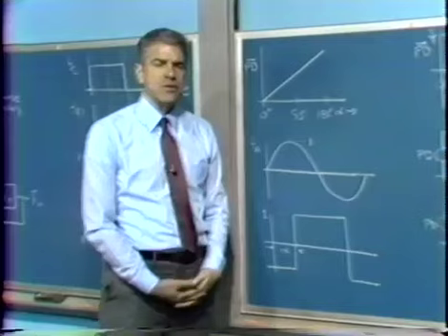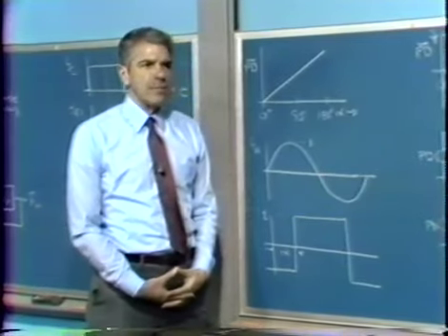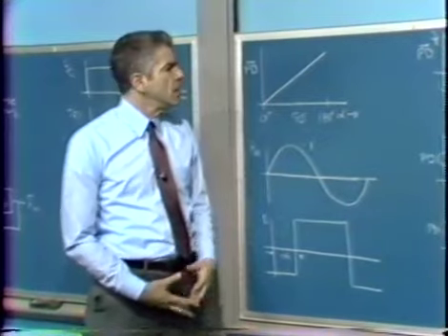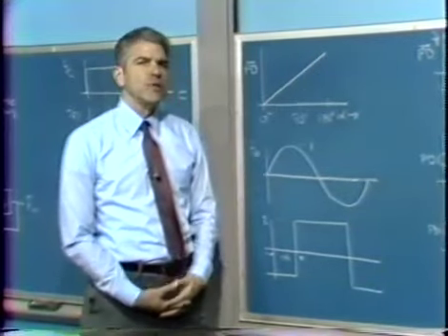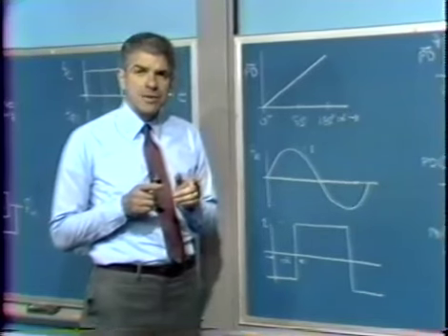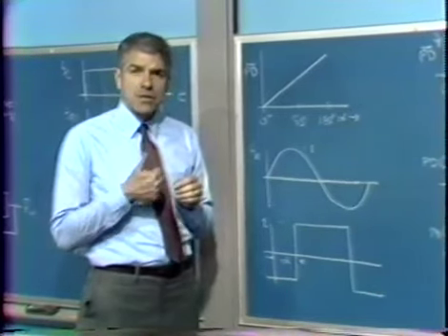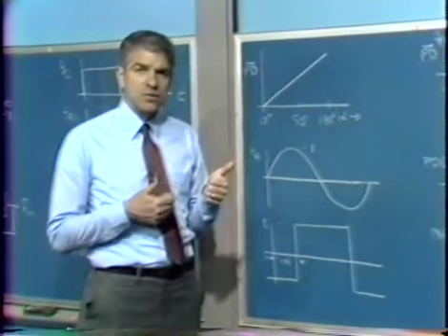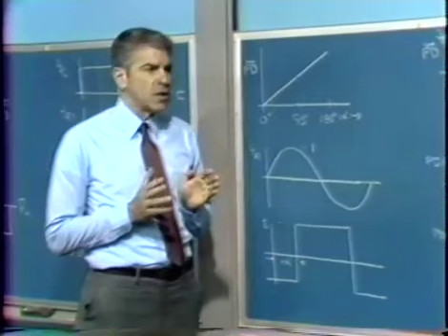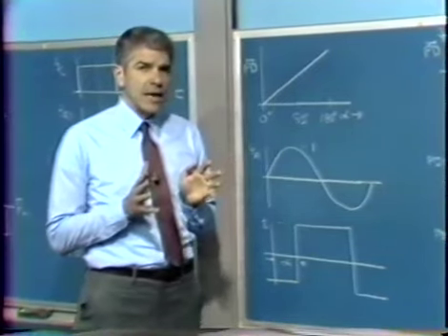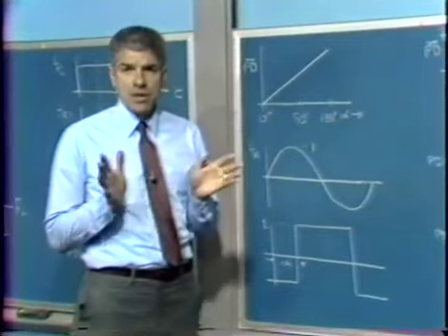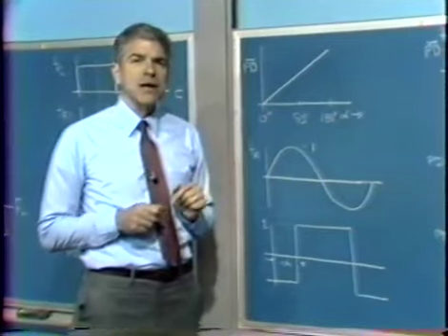There are a lot of other ways to do a phase detection. For example, we can get much the same kind of thing as we do in the exclusive OR gate, with a little bit of different detail about the way the pattern repeats, if we simply use a set-reset flip-flop as the phase detector. Set it on one of our signals, reset it on the second signal. Again, if the two signals in that case are 180 degrees out of phase, we'd find out that the duty cycle of the flip-flop would be 50%. It would spend half its time in each state.